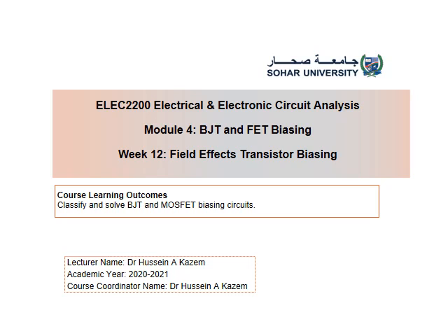And the graphical method was load line analysis, where we started from the input characteristics, the relationship between I base and V base emitter, and we take the results to the output characteristic, which is I collector with V collector emitter, and then we find the quiescent point. After that, if we want to find any voltage in the circuit, we can do so easily.